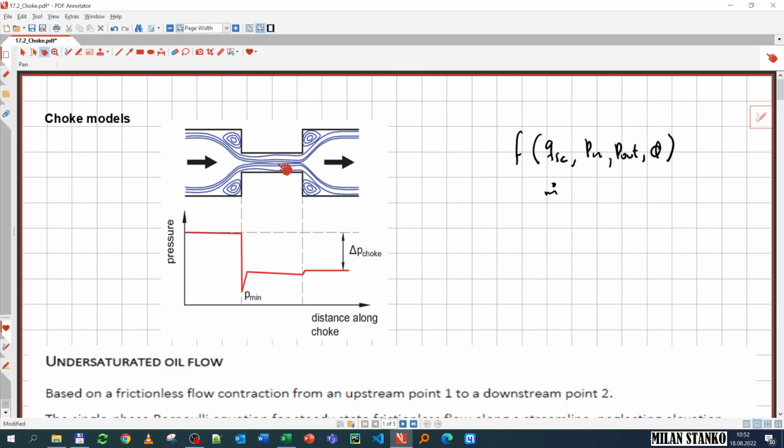One main issue with mechanistic models is that they are not very predictive out of the box, especially if you have multi-phase flow of oil, gas, and water. So you always need, besides the physical equations, some data to tune your results to the data to make them predictive.